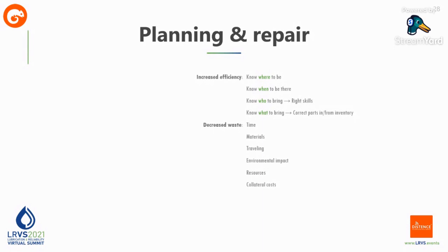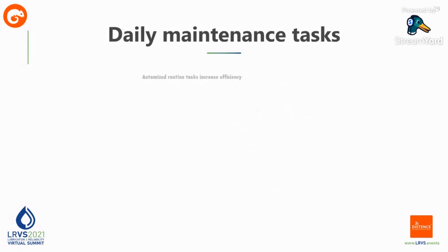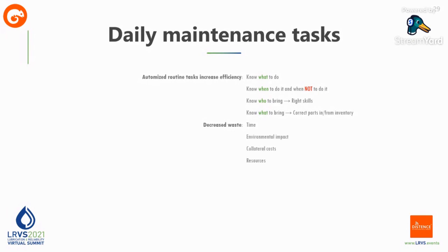For the client, this means shorter downtime and less collateral impact to production. Even the daily, for example, preventive maintenance approach gets easier. For instance, as highlighted earlier, by looking at data from different angles, the technology can improve scheduling lubrication intervals as you know how lubricant is performing. In practice, the system can predict when to grease, and you now also know when not to grease. Time-based grease schedules are a thing of the past and can now be replaced with need-based ones.